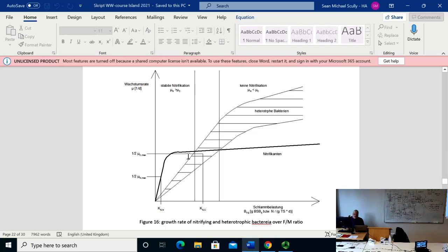course, is less, because if you look at it, in the aeration tank you have more COD than you have nitrogen, ammonia nitrogen. So there's more food for the heterotrophs, but you can lower the food for the nitrifiers to almost 0, and they still work at a full rate. No? So this is why you can get into this area.